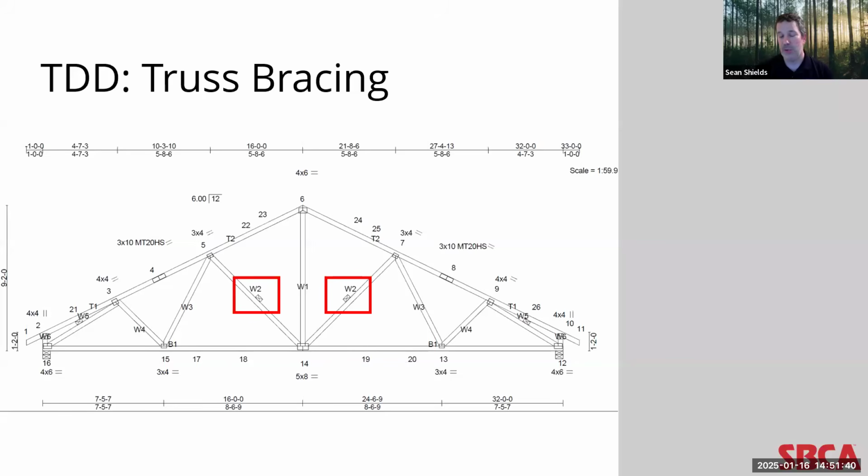And sometimes you just need one, and that would be called, for instance, a T-brace because of the shape or the letter it makes with its shape. Sometimes it's a U-brace. You can guess what that looks like. So sometimes that web member restraint is added as well.